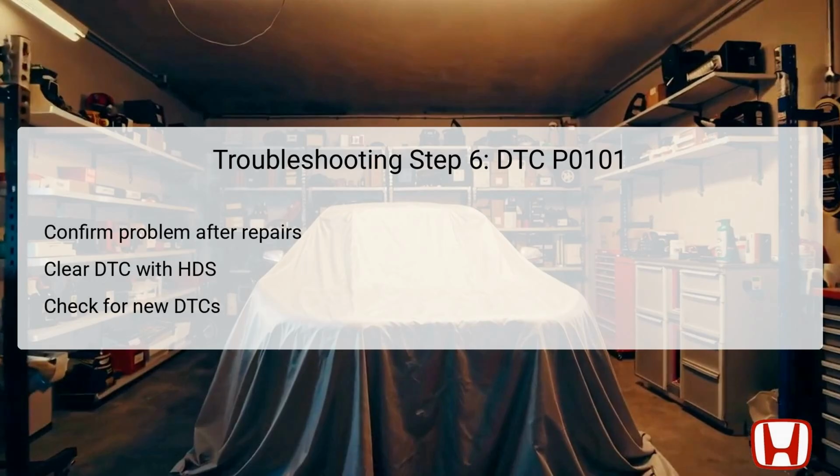Upon completion, recheck for any pending or confirmed DTCs with HDS. If DTC P0101 reappears, it confirms a recurring issue. Finally, if no codes are present, it suggests that the system is currently operating correctly, indicating that you should check connections and ensure everything is secured properly.